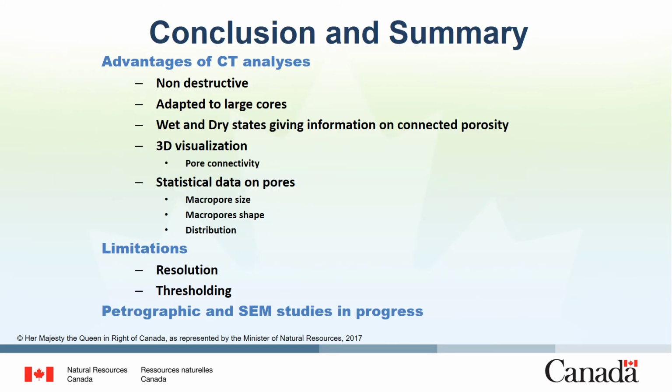Now, to conclude, there are several advantages to the medical CT analysis we developed and applied to Silurian karst samples from Southern Ontario. First of all, the methodology is non-destructive and can be applied directly on large core samples. Secondly, the two-state saturation protocol and the numerical comparison of wet and dry datasets give information on the connected porosity. The methodology also offers powerful 3D visualization, giving insight into the pore connectivity in 3D. After segmentation, we have access to statistical data on pores and the pore network.